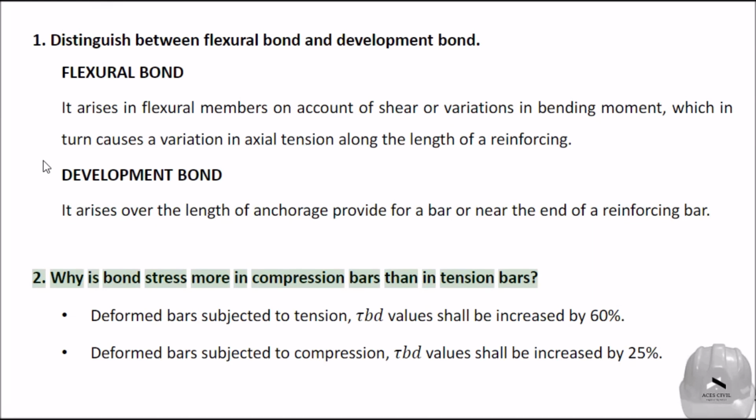2. Why is bond stress more in compression bars than in tension bars? Deformed bars subjected to tension: values shall be increased by 60%. Deformed bars subjected to compression: values shall be increased by 25%.